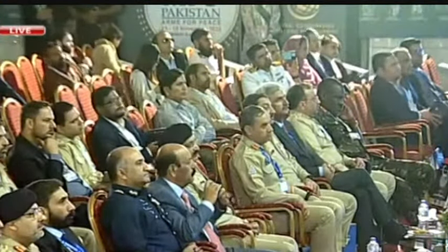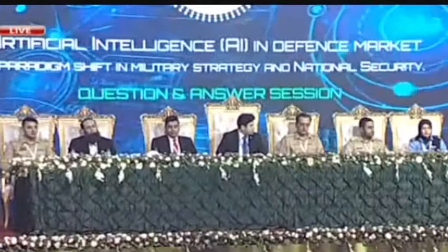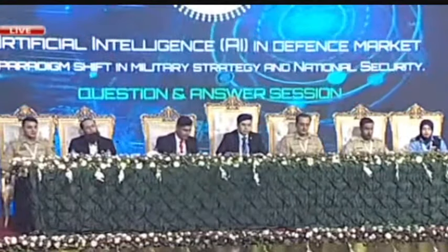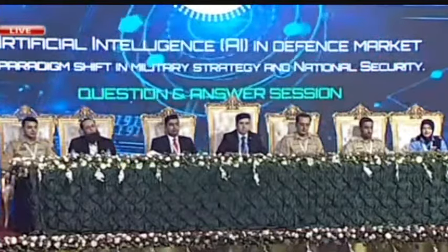Thank you for your question. Actually, you have rightly pointed out that FOD detection is a complicated problem because FODs are small objects, and we have a deliberate FOD prevention program on all the airports and airfields. However, the world first realized why automated FOD detection is important after the Concorde crash, which happened because an aircraft that took off 5 minutes before dropped a piece of metal. Humanly, it is not possible to inspect a complete runway within 5 minutes.